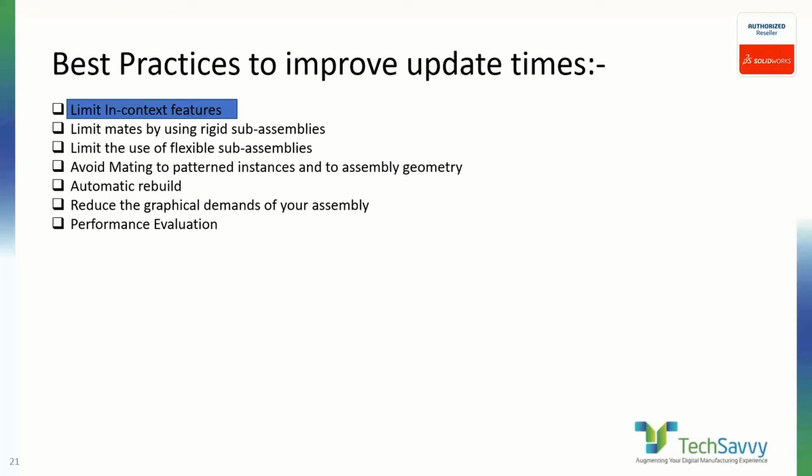If you have multiple in context components, this continues for each one. This process can be time consuming as the total number of regenerating features grows. Imagine 30 components that have 10 features that are in context or dependent on an in context feature.